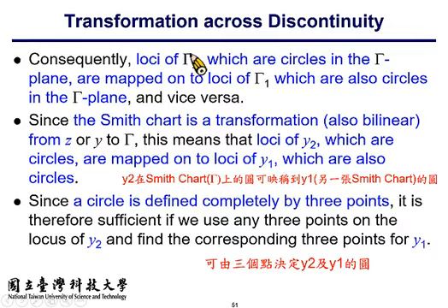Nevertheless, the magnitude of the reflection coefficient remains constant on this constant SWR circle. However, in the following example you will see that by connecting an extra element in shunt or series configuration, you can change the locus of the reflection coefficient.